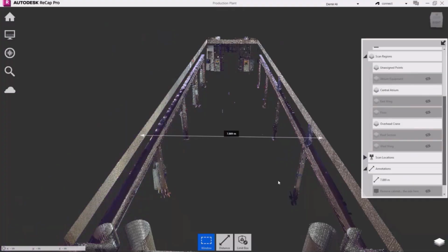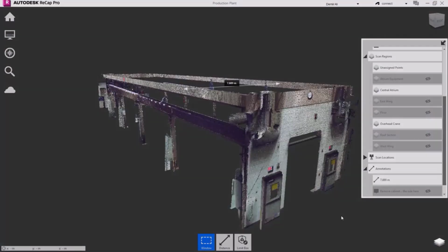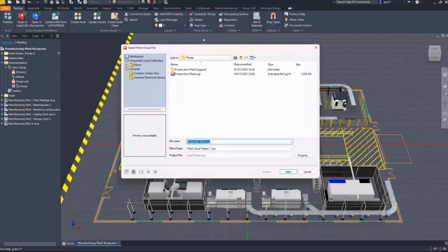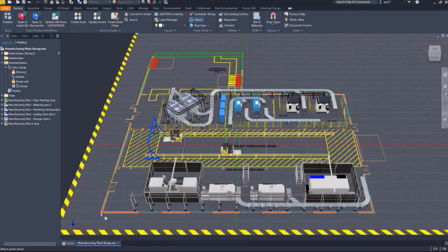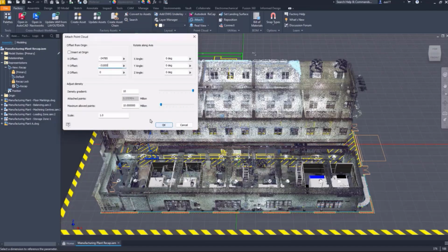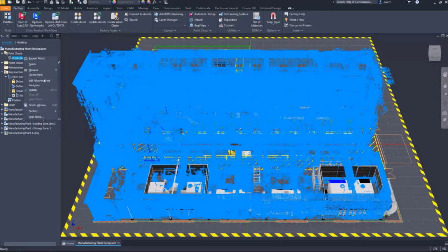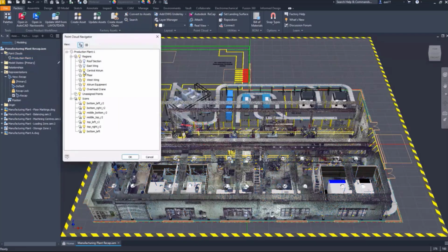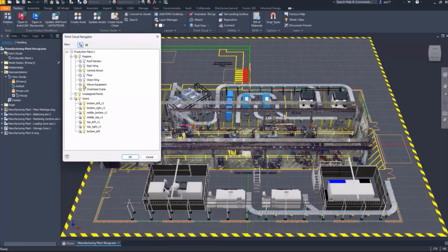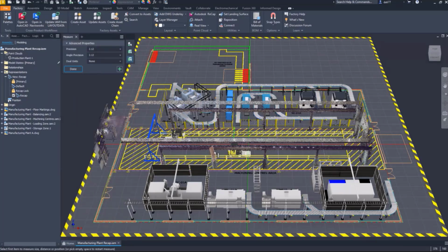Like in this screen you are seeing now, this is the area that we want to focus on, because this is the factory floor that we want to use to insert our factory stations. So now let's place the point cloud data. The point cloud data that was just processed, we can put into Inventor. This is the Autodesk Inventor interface. Let's place it. You can see that I now have control of the point cloud data. I can hide or suppress whatever I do not want.